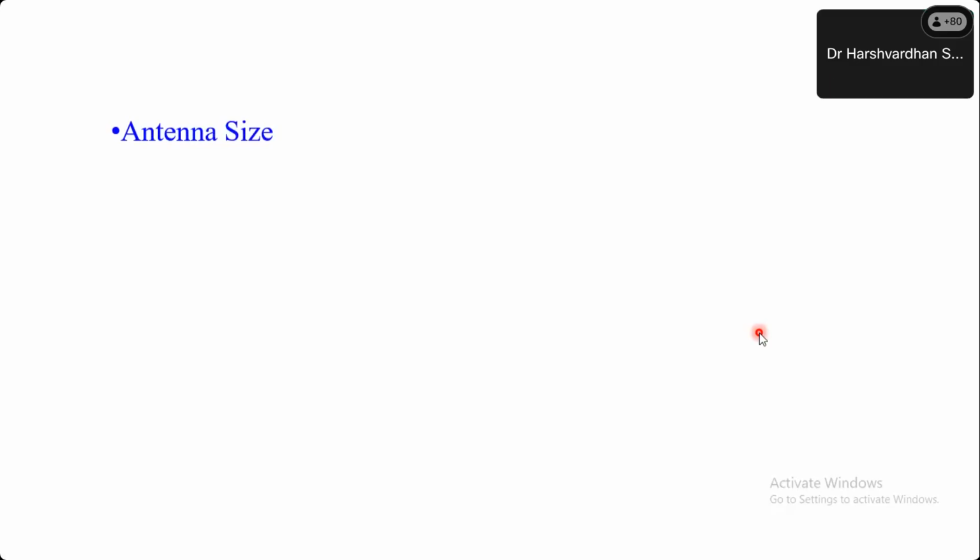So in that case, you need miniaturization of the antenna. You need to make the antenna compact, even while it works at that frequency, by reducing its aperture. Now, as you start reducing the aperture, what will happen? The antenna's gain and radiation performance will drastically reduce.